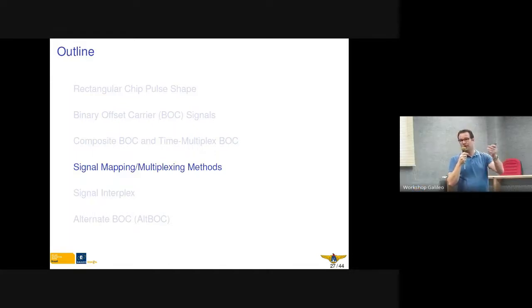But now with Galileo and Beidou all pressing into the same bands as GPS, and also GLONASS in its modernization entering the L1 band, for example, we see that there are more signals being transmitted, more services provided by GNSS today in the same bands, and this spectral separation will become more important, I think, in the future to manage the interference between the systems.